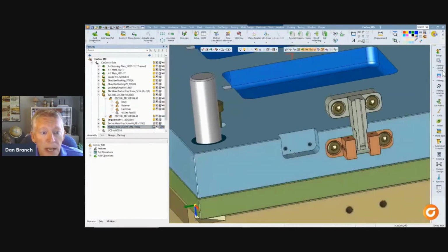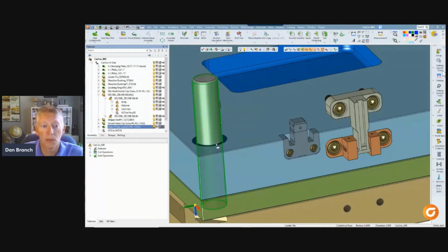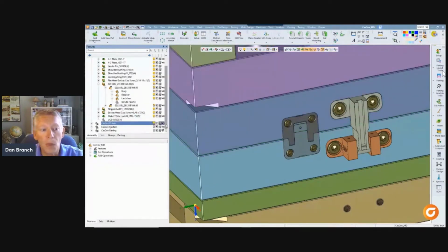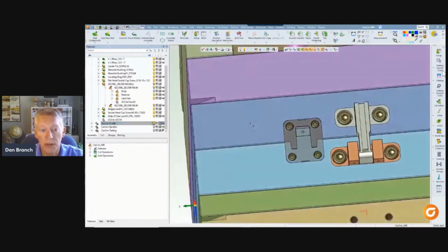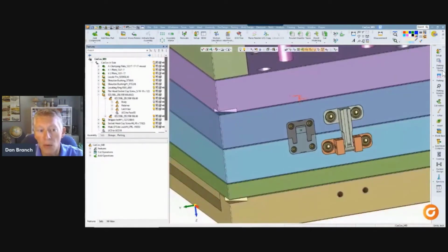Now, by hiding those newly added parts, I can verify that the pocketing looks good. This ability to cut in the pockets comes right from the smart catalogs. The type of pocket and clearances are all relative to the parts, so no matter what edits may take place later, I can be sure that the plate machining work is going to be correct. Now, as expected, the B side of the tool received the rest of the side lock components and, of course, the corresponding mounting holes.